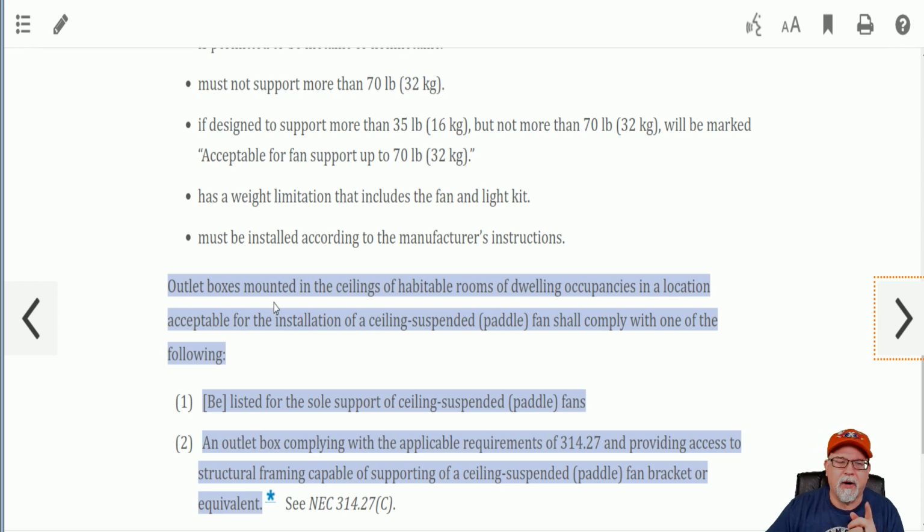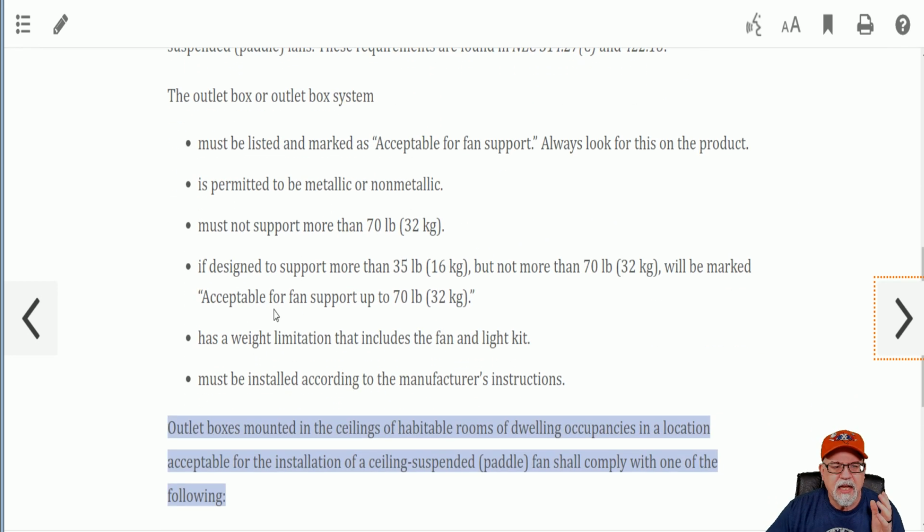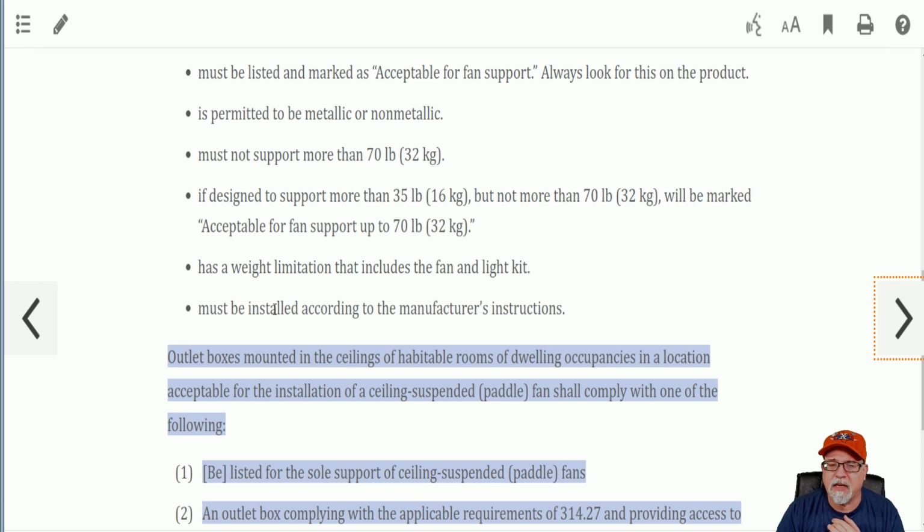And lastly, with that first component, you need to make sure that you follow the manufacturer's instructions. Even ceiling fan installations have instructions. They're a part of their listing. Many people throw those away. But if your inspector ever came on site and said, I want to see the instructions for the installation of that ceiling fan, they have every right to do that, and they could require you to show that. So I wouldn't just toss them. Put them in a kitchen drawer or something like that, so that the homeowner has them in case somebody asks about them. You want to make sure that you have them available.